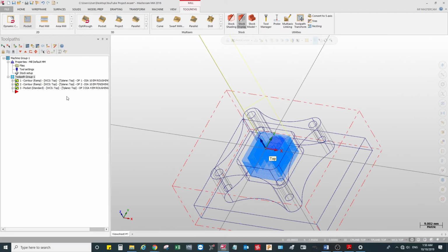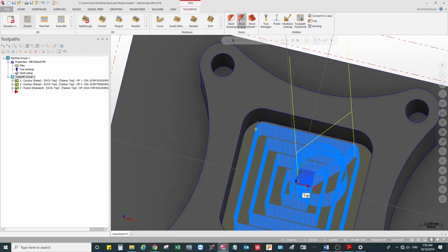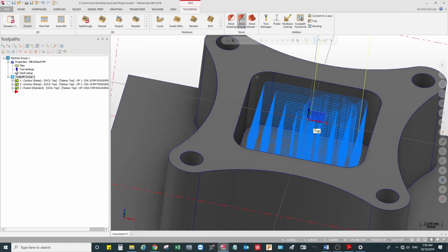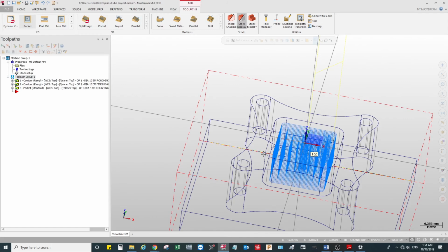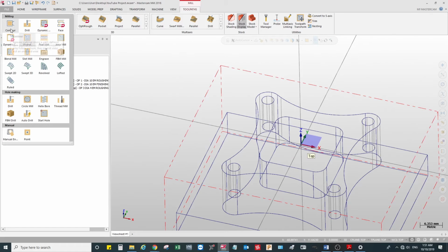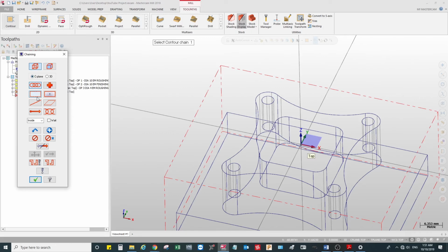It's safe. Then this becomes your third operation. So you put op 3, dia 4 end mill, roughing. We'll give 0.1 millimeter as the stock for this third operation. So there you go. So machinists can see what this particular tool path will entail.